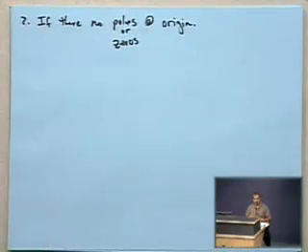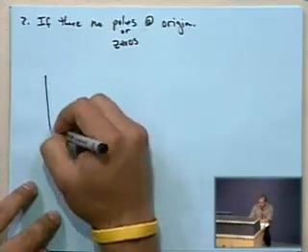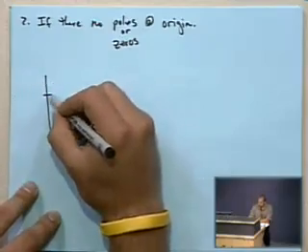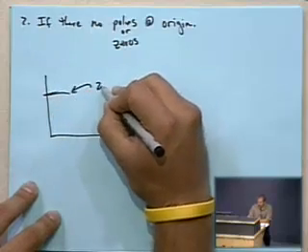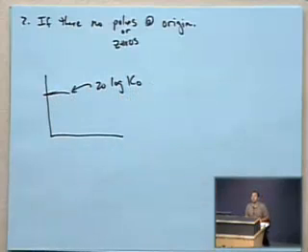That one works out very nicely with the kinds of things that we saw before, because basically what's going to happen is that it will start out at some magnitude, and it will do whatever it does, but it will originally start out at a magnitude which is 20 log base 10 of k0. And then what it does from there depends on the rest of the transfer function, if you have zeros or poles beginning to affect the frequency response.